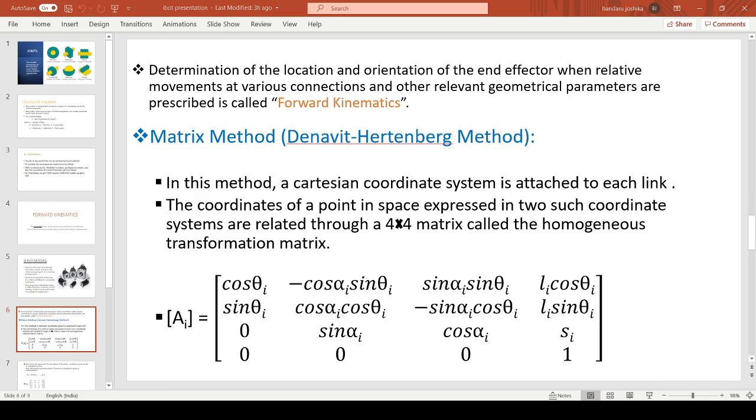Most industrial and other robot manipulators are based upon an open kinematic structure with the operational unit called the end effector or gripper placed at the end of the open chain. The primary objective of a manipulator is to place the end effector at a desired location and orient it in a desired manner. There are two basic problems in kinematics of open chains.